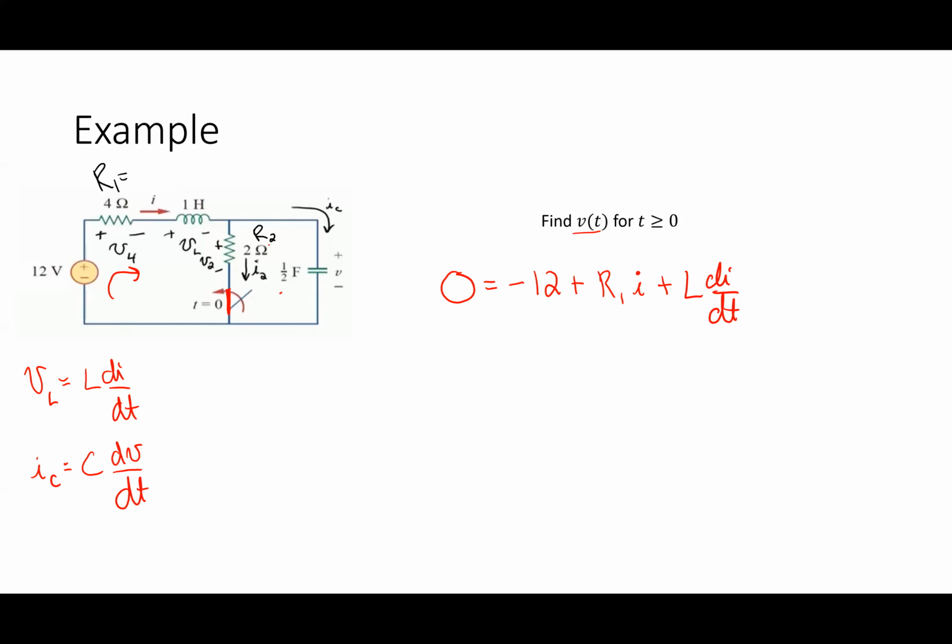So what's the voltage across the parallel combination of the resistor and the capacitor? VC. Yep. I'm just going to write plus the capacitor voltage. Now that's good for me for now, right? I'm happy with that because I want to get to the capacitor voltage. What else do I need to do? I want a differential equation for the capacitor voltage. I want to get rid of the current. I don't want the current to be here.